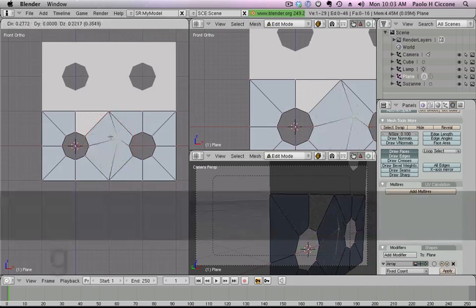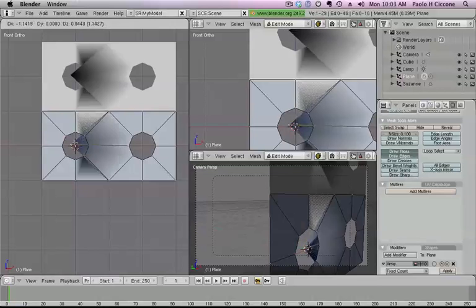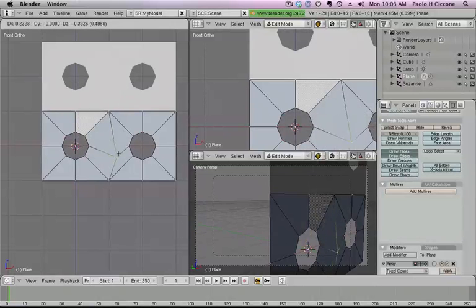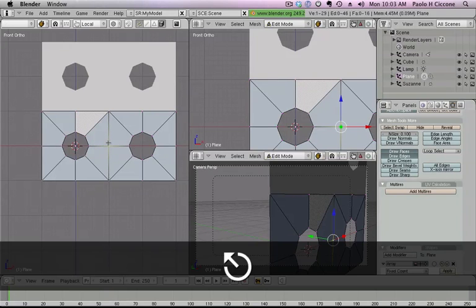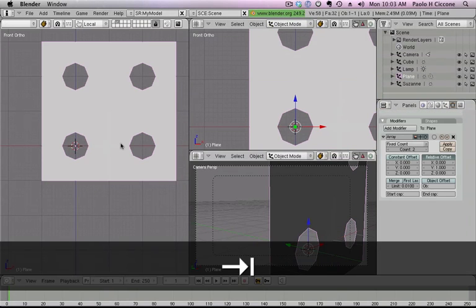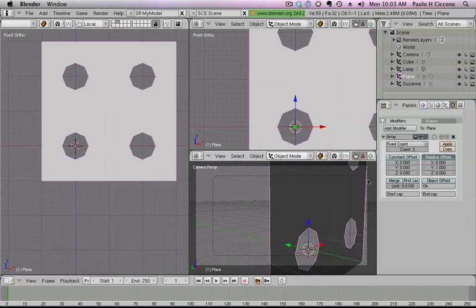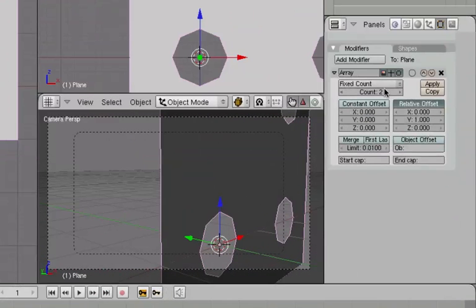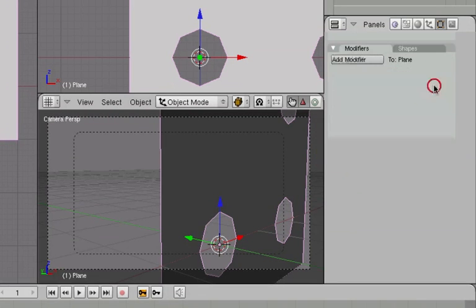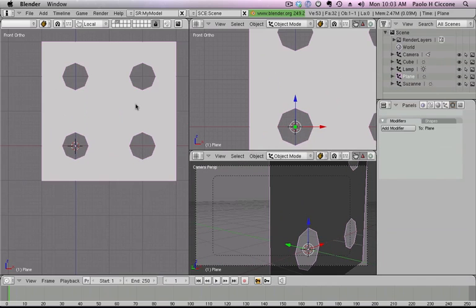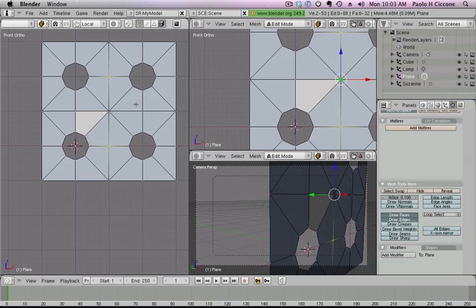Good. So if I click on, for example, the vertex select mode, press A, and I select this vertex and I move it around, well, we see it affects all the polygons connected to it, and they're all connected at this point here. Great! So let's repeat the experience. I'm having fun with this. We have our modifier here in the vertical direction. Click on Merge, Apply, and Tab to edit mode.